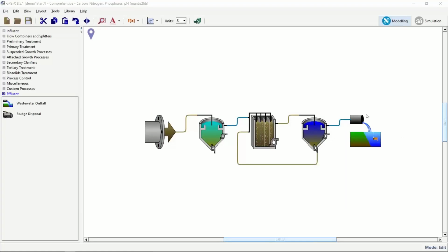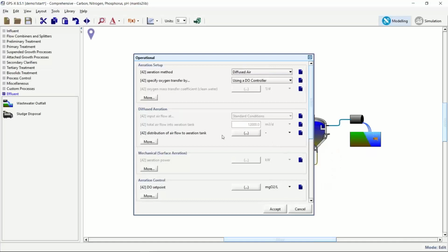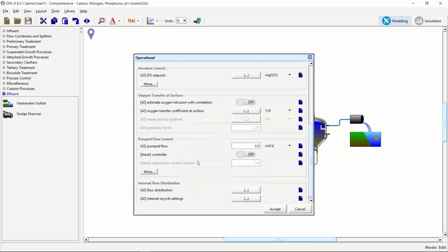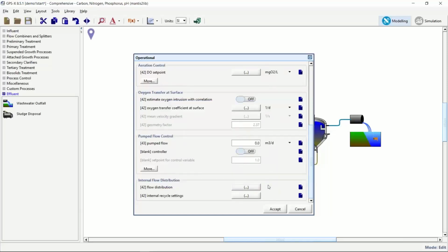So what we need to do now is go back to the influent part and slide down to the bottom. And now we'll see that we only have 3 reactors and 100% of it is going in the front end here. Okay, same thing for the RAS. The connection point that's on the lower side of the left is coming in, and that's also 100% of it going in the front. Okay, so no changes to be made here, but we did check, and this is where you would make the change if that was part of your BNR design.